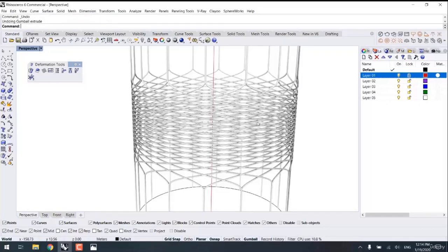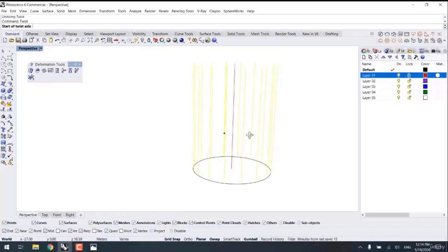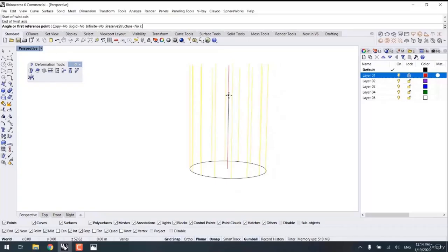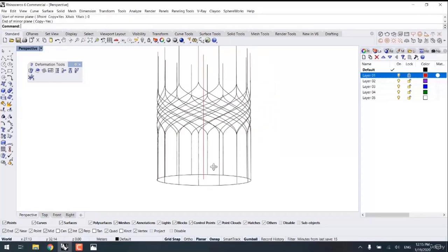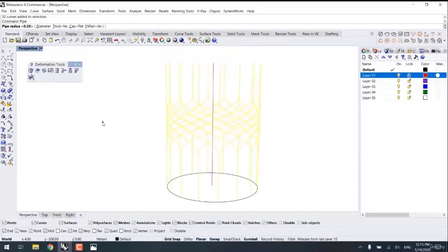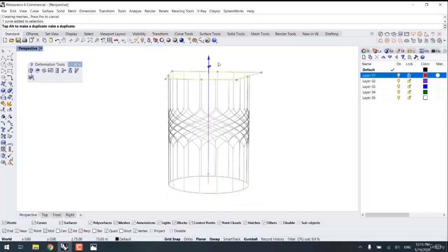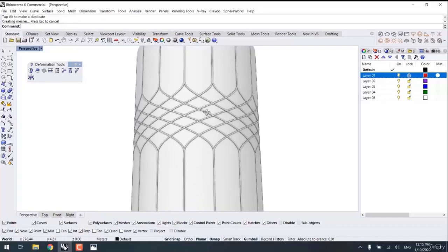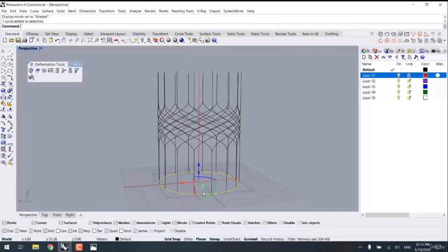And if we want to maximize the size of the openings between the pipes, then we can specify a lower value for the rotation angle. Check it out, for example 90 degrees, and then we mirror it. Let's check it out. Then the openings of the pipes, as you can see, are greater than before. And then pipe, check it out. So by just modifying the rotation angle, decreasing it, we could modify the density.